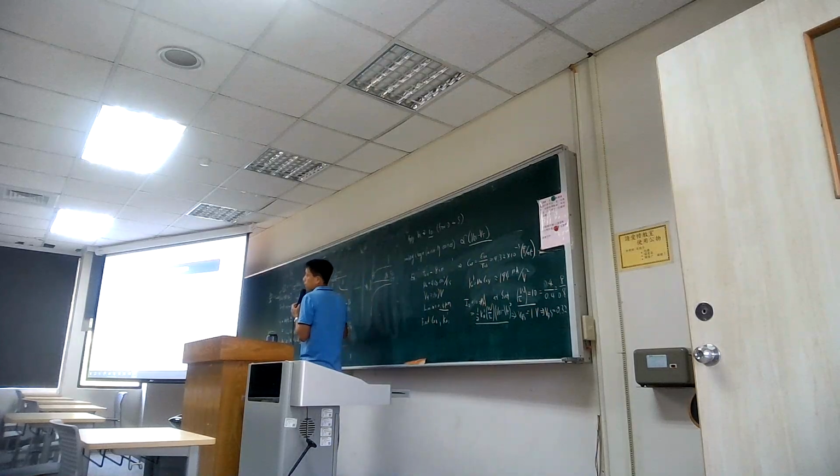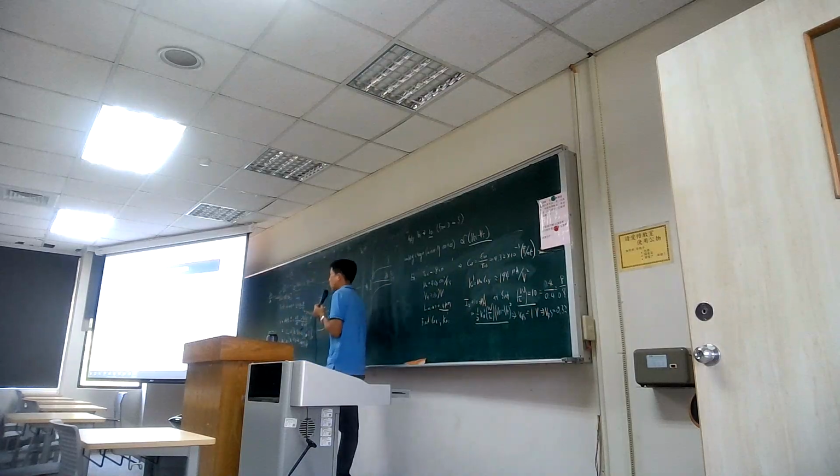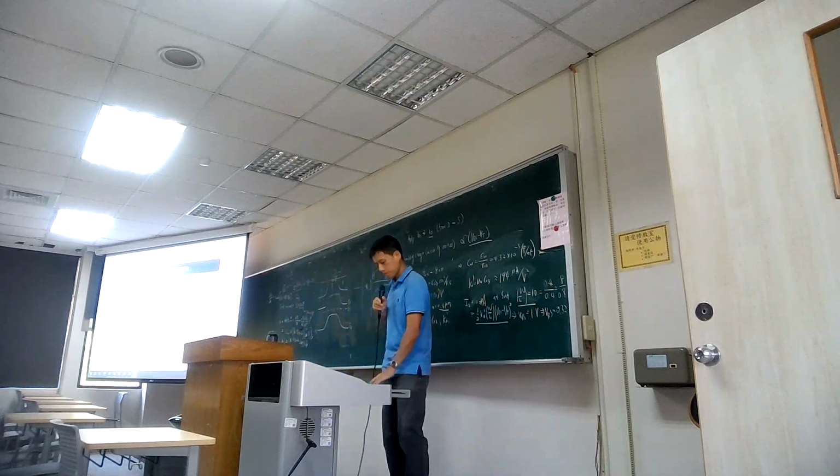So you split the Fermi level, but the split will be only related to the minority carrier by the drain voltage. Before we apply any drain voltage, the Fermi level will be still the same for both EFN and EFP. There's only a single Fermi level. But later on, when you apply the reverse bias at the drain part, it's just like reverse biasing a PN junction. We split them for the minority carrier, but for the majority carrier, that will still remain the same.